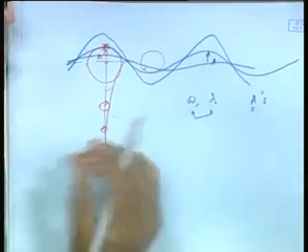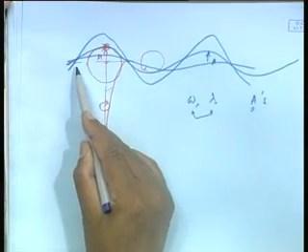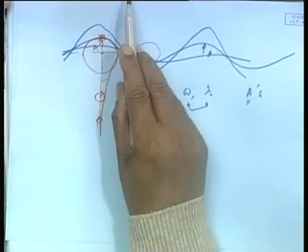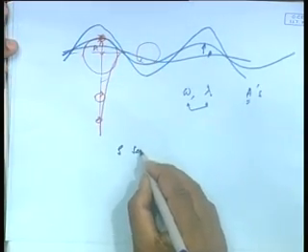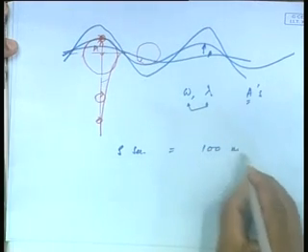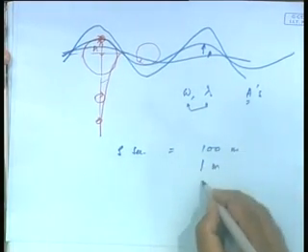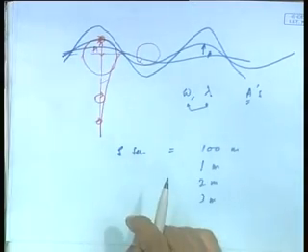In other words, the dispersion relation is connecting my quantities in the horizontal axis, time axis and x axis, but nothing in the vertical axis. In other words, if I have an 8-second wave, it is 100 meters. What is the height? Well, a 100 meter wave can have a height of 1 meter, can have 2 meters, can have 3 meters. This is not specified.